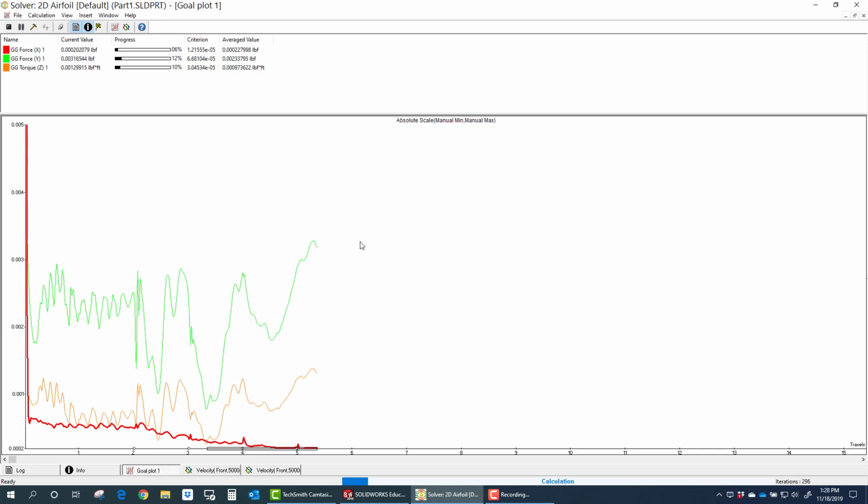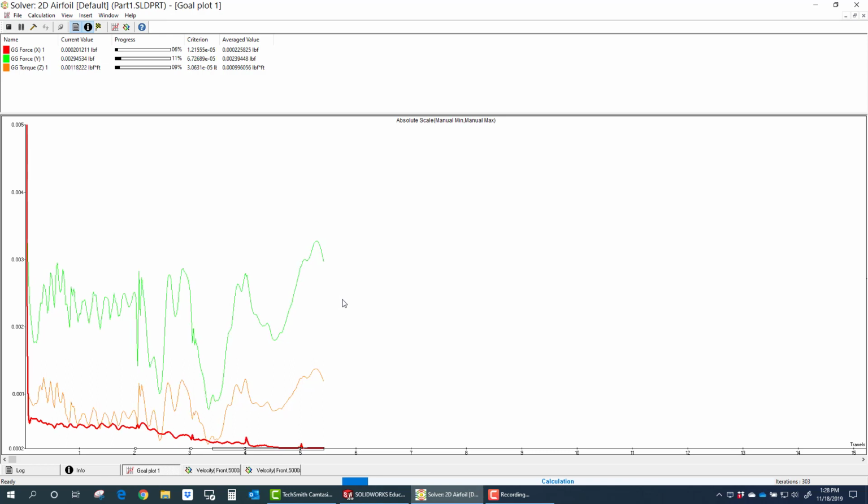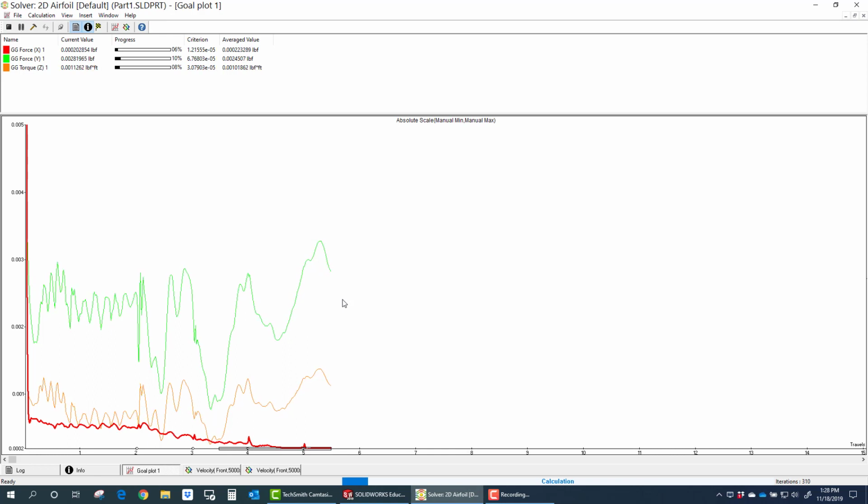Your best indication of convergence is after several different mesh refinements have happened. You don't get any change anymore. And so you might have to run your first test case with any geometry for quite a long time and let it refine to as much memory as you have, and look at the convergence characteristics of the job you're running.